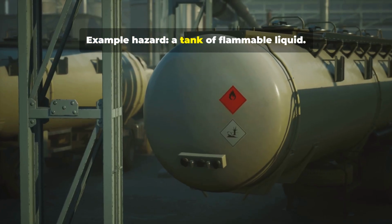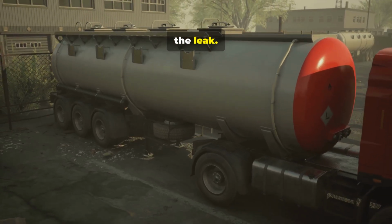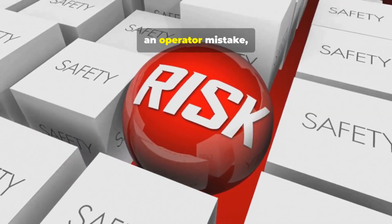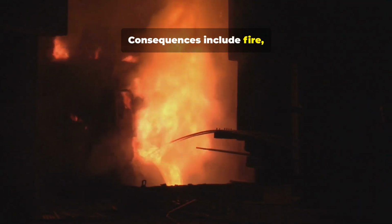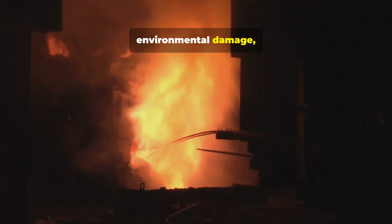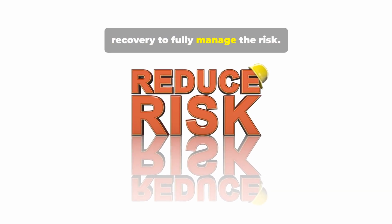Example hazard, a tank of flammable liquid. Central event, a loss of containment. The leak. Threats include corrosion, an operator mistake, and a vehicle striking the tank. Consequences include fire, explosion, environmental damage, and harm to people. A bow tie balances prevention and recovery to fully manage the risk.